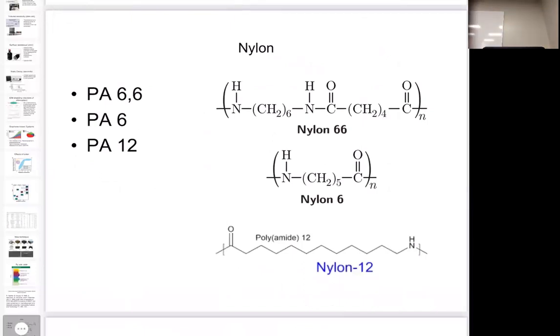The polymer is really good because it is melt processable, it's fairly inexpensive, and it's got a nice hydrogen bonding group and a polar group, so that if you have functionalization, it will help disperse. The top one here is nylon 6,6, and the reason it's nylon 6,6 is you have 6 carbons in between those 2 nitrogens. You have 6 carbons on this thing too.